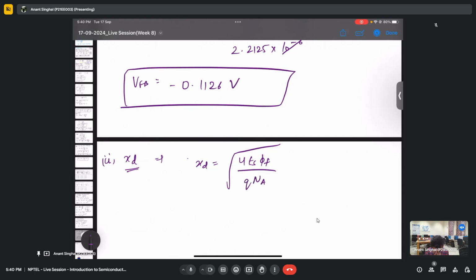Maybe you can give the answer quickly. And I hope you have the clarity that for the depletion region we will use the epsilon for silicon. For the oxide part that we were doing earlier, for the Cox, we were using the relative epsilon of the HfO2. So in this, the epsilon relative will be 10, that is given in the question. Is this clear?